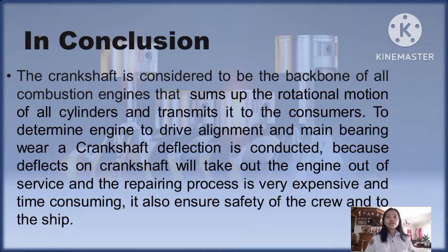To determine engine to drive alignment and main bearing wear, a crankshaft deflection is conducted, because a deflection on the crankshaft will take the engine out of service, and the repairing process is very expensive and time consuming. It also ensures the safety of the crew and the ship.